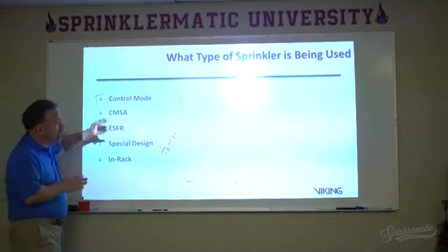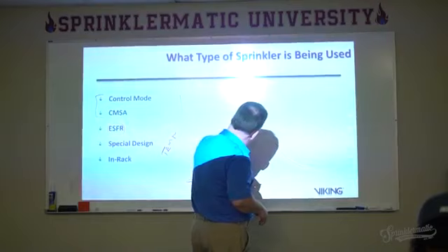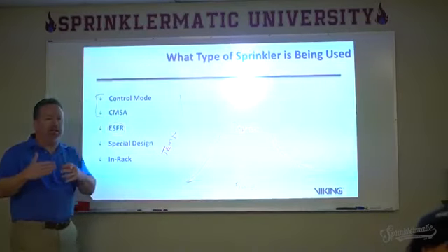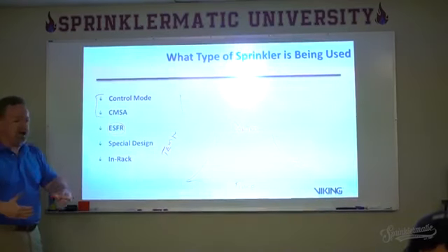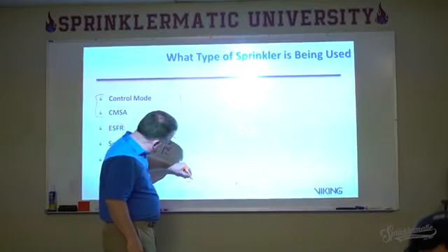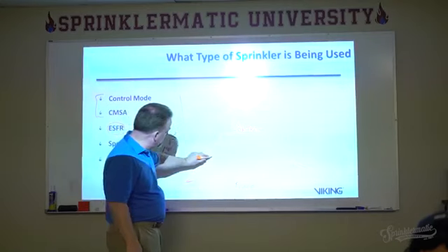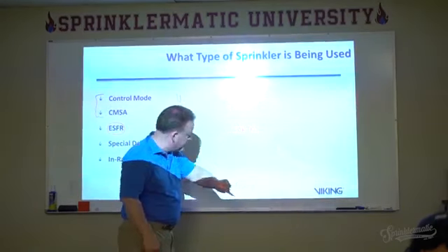So we went from this control mode up here to actually being able to suppress the fire. Put enough water on that fire to actually, as it took off, it would do this. The ESFR sprinkler would kick on, and you'd go down to this.